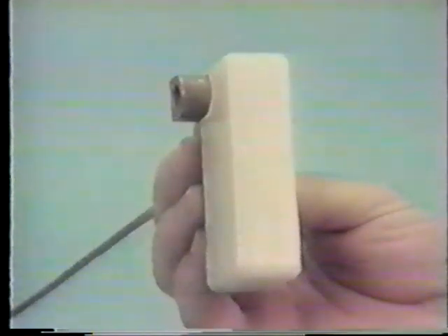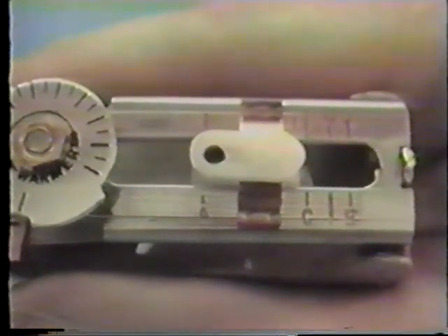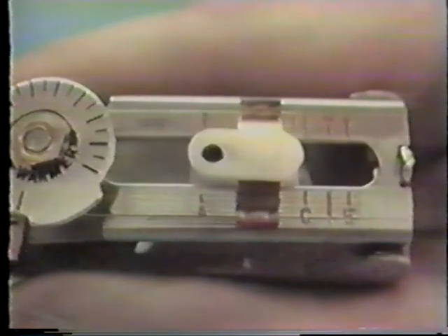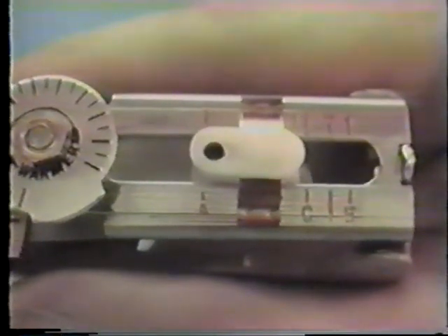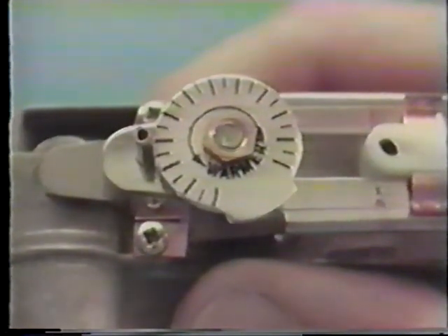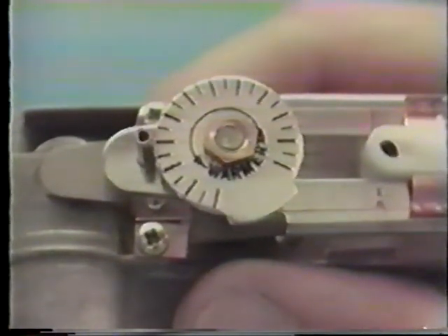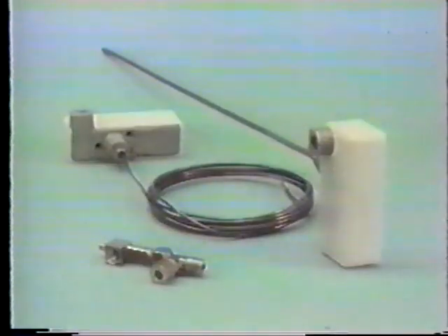Field adjustments are easily made by removing the snap-on cover. The throttling range is adjustable from 10 to 50 degrees Fahrenheit by means of the slide adjustment. Each graduation represents 10 degrees Fahrenheit. The set point adjustment is made on the graduated dial with each graduation equaling 5 degrees Fahrenheit. The temperature range of the device is 40 to 150 degrees Fahrenheit. Two bulb styles are available on the Airstream controller, a 19.5-inch rigid stem and an 8-foot averaging element. A fixed external restrictor is supplied with the unit.